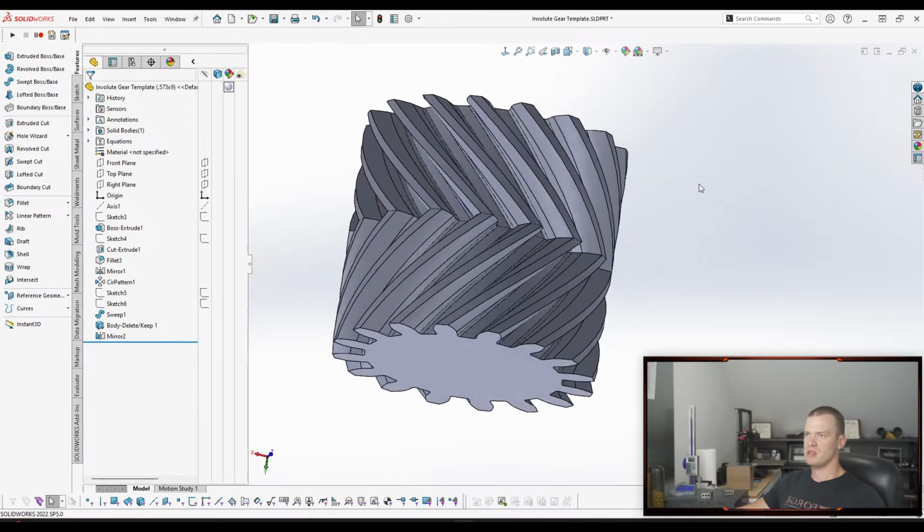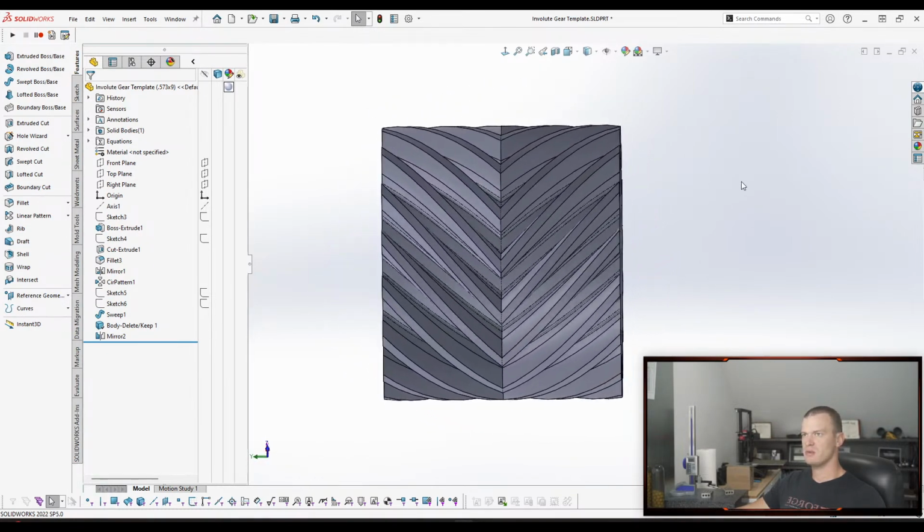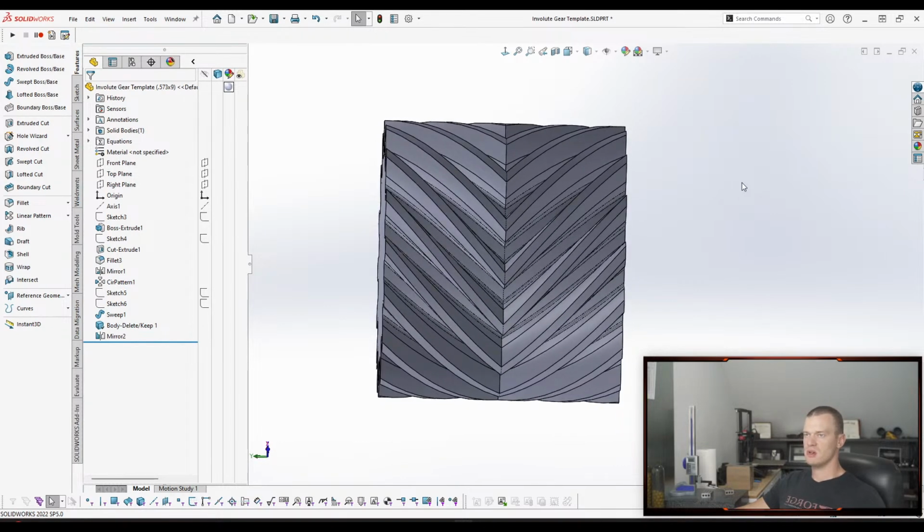But that to me would be the way to do it. And the benefit of using this type of gear is that you don't have any axial force anymore. A spur gear doesn't have axial force because the teeth are straight, but as you crank up the helix angle, you're getting additional power transmission because you're spreading the load out over more teeth, but now you're also inducing axial load down the shaft that the gear is riding on, as the angle of that tooth is now pushing